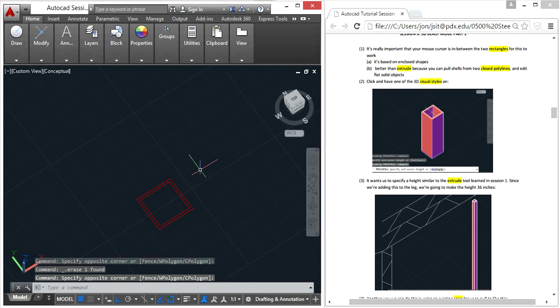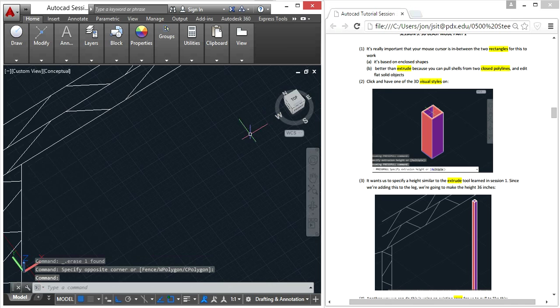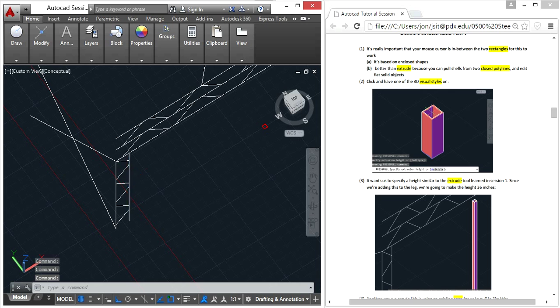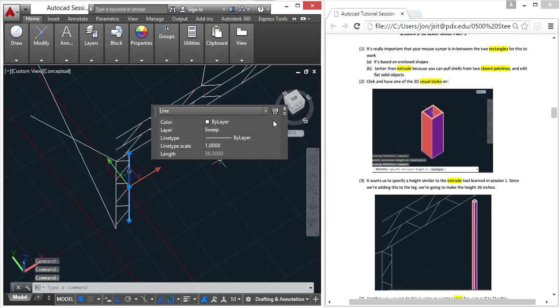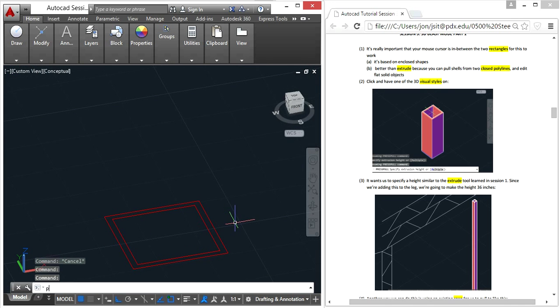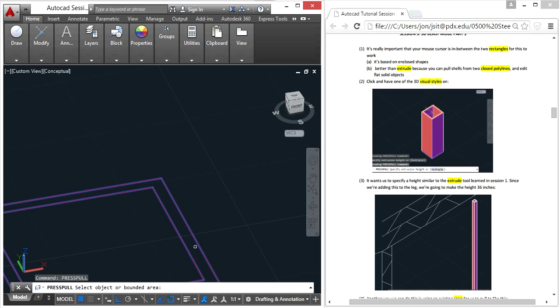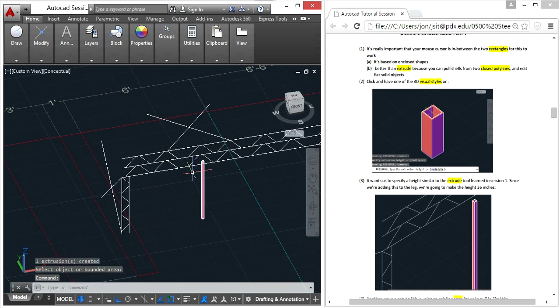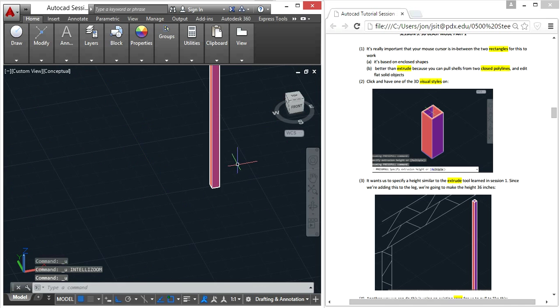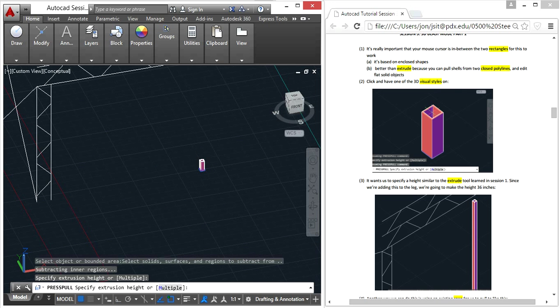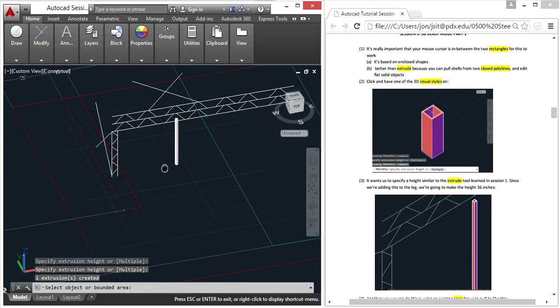So we need a certain height, and I know that I'm going to add this to the leg. So that's how I'm going to start this off. And the leg is indeed 36. If I double click, it tells me the length is 36. There are 2 ways I can do this. I can type Presspull or press, make sure the 2 solid lines glow, type 36, and bang, it makes me a 36-inch tall tube. Since it's on the XY plane, I can also pull it and click on something for it to reference, and it's the same thing.